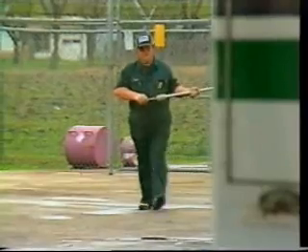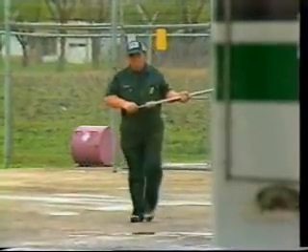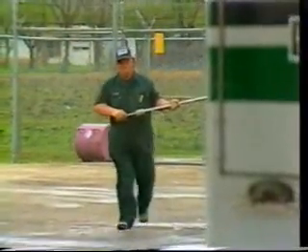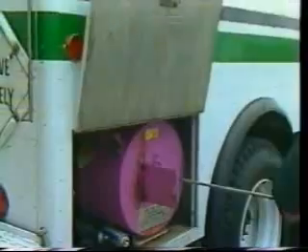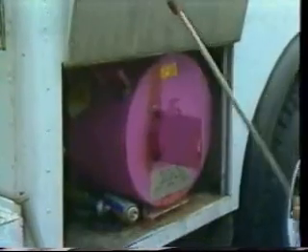You'll learn more about industry standards and how each type of logging device is calibrated in GL 402, well logging tools and techniques. As loading of the logging unit continues, radioactive sources for nuclear logging tools are transferred from their secure storage area to a secure carrying compartment in the truck.